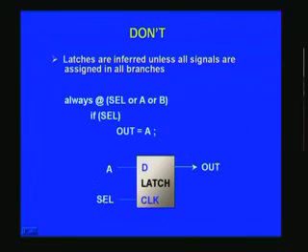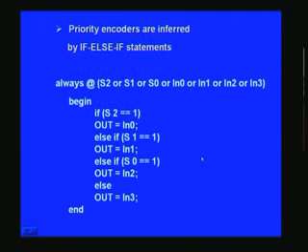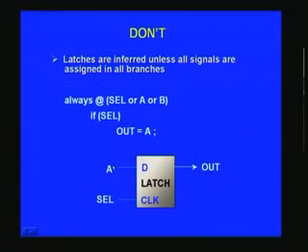That is, when the clock is not applied, whatever is applied to A will, without any hindrance, appear at the output. And what will happen here? It keeps on changing here. And if you have mixed it with a synchronous circuit, it may register at an undecided point. So you should avoid these latches here. And the reason for creating a latch is that you have omitted the else.